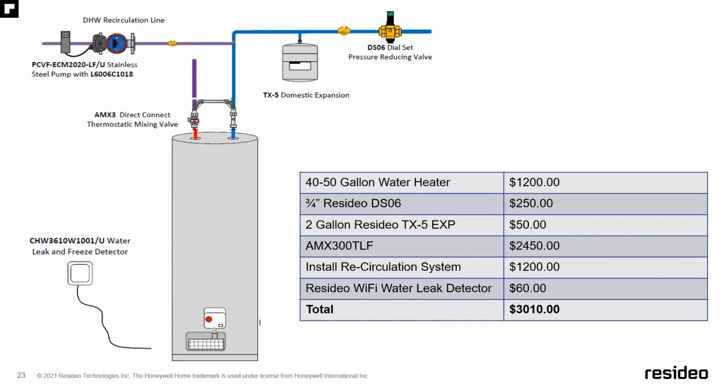Expansion tanks. We talked about that earlier. Ma'am or sir, you have a double check valve assembly on the house, but you don't have an expansion tank. This is why your tank is bad. So before we put in this new tank, and you're going to spend $1,200 to $4,500, whatever it may be, on this new tank, we're going to want to add in an expansion tank. This will increase the longevity of the new tank and ensure that you are getting the most value from this install.